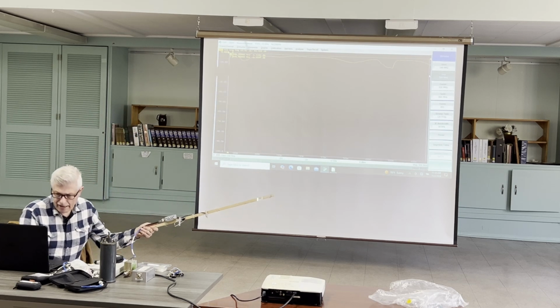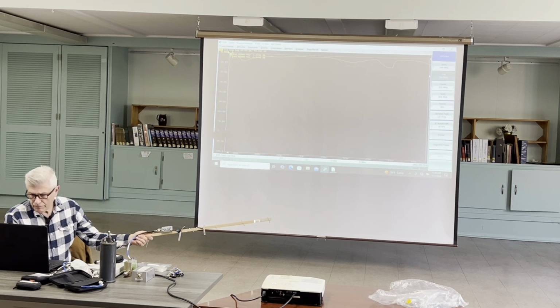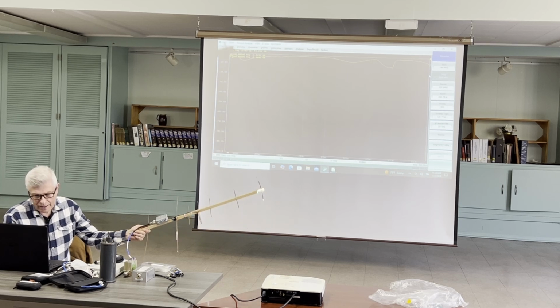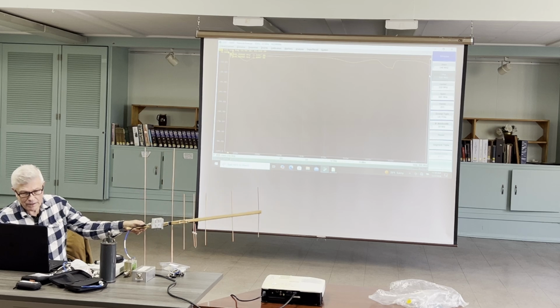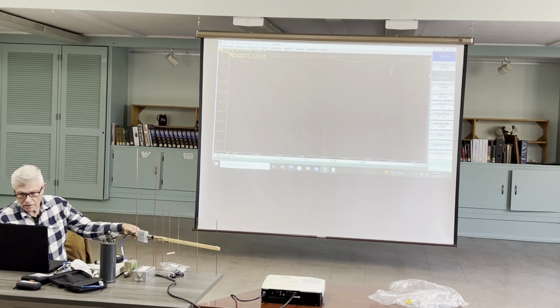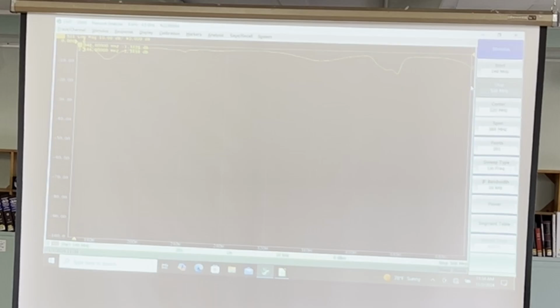Well, we have your resonant frequency looking like this. I've got to see if I can minimize the, there we go. We can get this minimized, but it looks like you got 2 resonance points, which you're a little high, Lou. You're about 162 on the VHF side, and maybe a little low on the, you're about 430, 438, something like that. So it is indeed a dual band system.